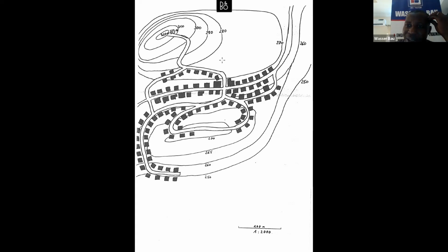That's why in water design, the first person that goes to site is your surveyor. The surveyor should go and take spot heights and know the levels. In fact, for any infrastructure work you want to do, whether sewer, stormwater, water, or even road, it's always the surveyor that goes, because the surveyor will give you the X, Y, Z. It is the Z that we're interested in, and that is what you can see in this contour line. The black dots you are seeing are houses, and these are the roads.